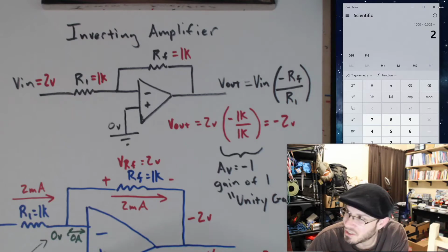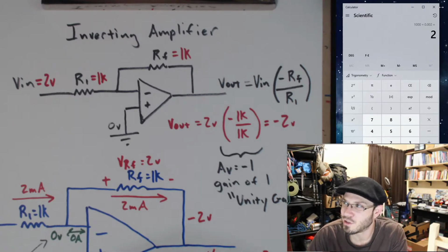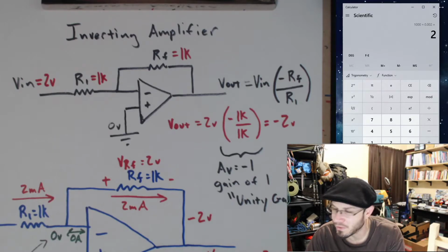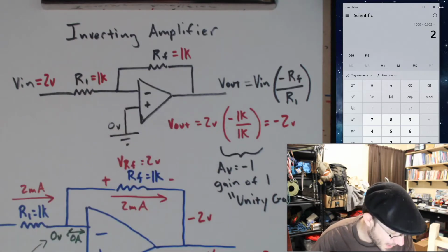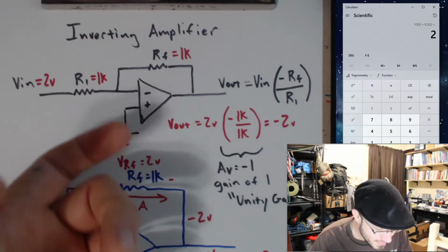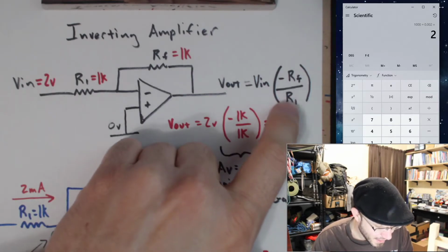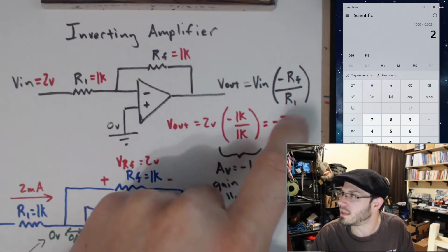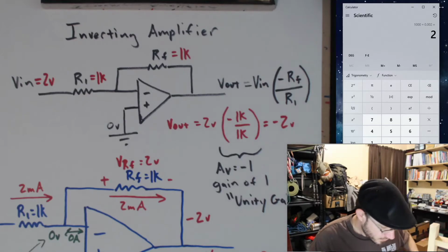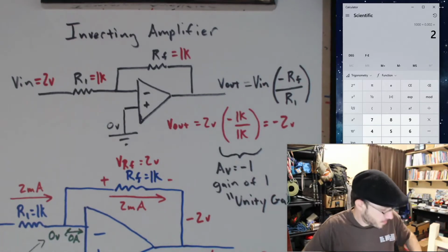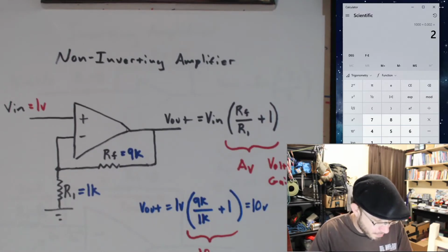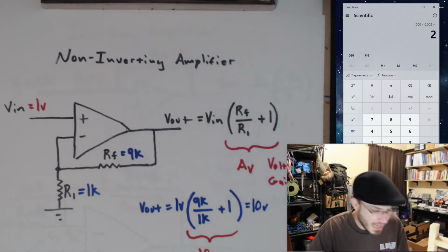If I have a sensor and I'm tying it to an embedded system or any type of digital device, and I'm going to take measurements, I may care about the polarity. So just keep that in mind. The inverting amplifier is nice because I can get gains that are either 1 or very close to 1, but they are inverted. And I have a non-inverting amplifier that cannot have a gain of 1.